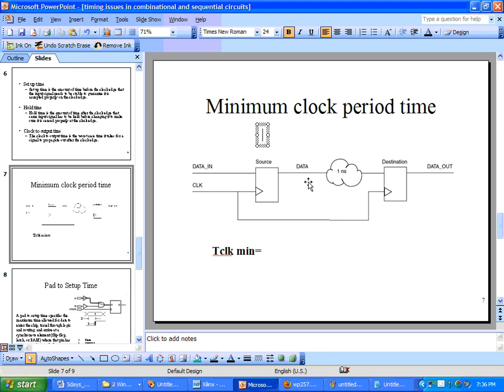The two flip-flops we are using have some characteristics. Setup time is, let us say, 2 nanoseconds, and hold time is 1.5 nanoseconds, and TCO, that is the clock to output time, I want to take some odd number so that we don't get confused, let us say 2.5 nanoseconds. So with this example, we will first work out analytically, then we will see how the equation of TCLK minimum evolves.